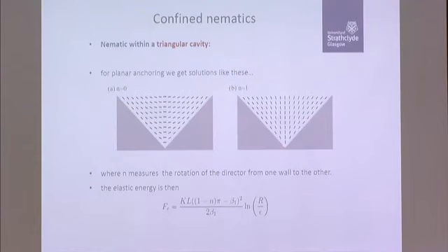And I can analytically work out the elastic energy, and it depends on a couple of things. It depends on the wedge angle, which we would expect, and it depends on the region size. I have to do the integration here up to some region, some radius R, and it depends on the defect core size. I also have to cut out a little bit of the core here to do this integration. Okay, so I've got this analytically.